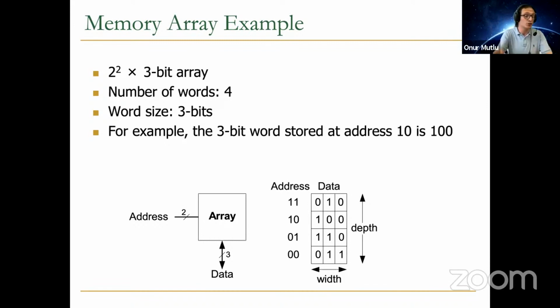As a result, you don't read thousands of bits, you read literally 64 bits or so, because otherwise you'll have huge interconnects. And especially if you're reading off chip, then you need to be very careful, because whenever you're reading off chip, you need to have pins to go out of the chip. And those pins are extremely costly. And you may not even have thousands of them, because they occupy a lot of area. Your chip may not be able to accommodate thousands of pins.